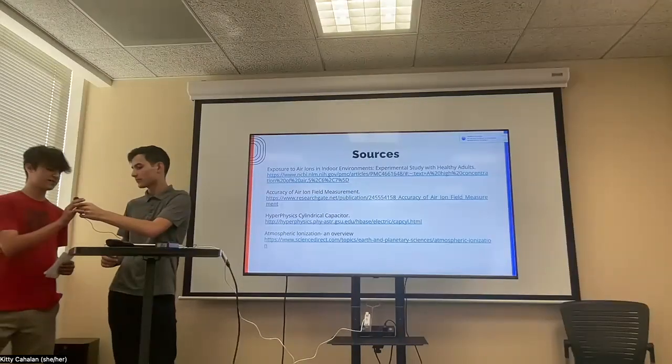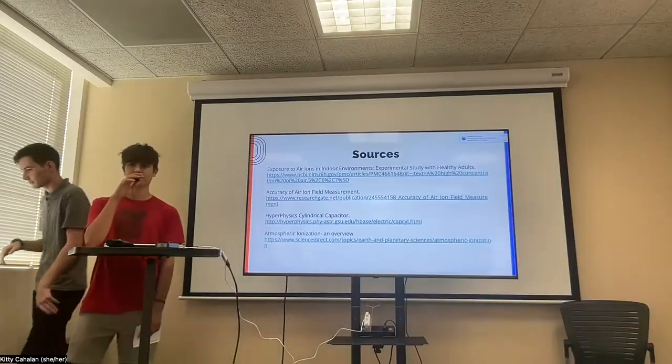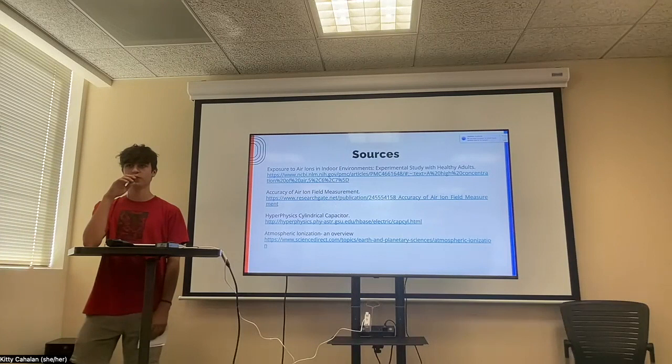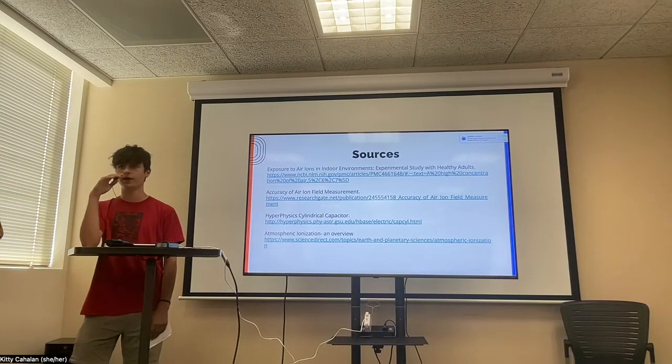That's why in my data, what I did is a min and a max over a period of time, because it would fluctuate on the order of 10 millivolts. And I think the method that I did, taking maybe 5 or 10 measurements, the min and max, and an average between them, is the most accurate.